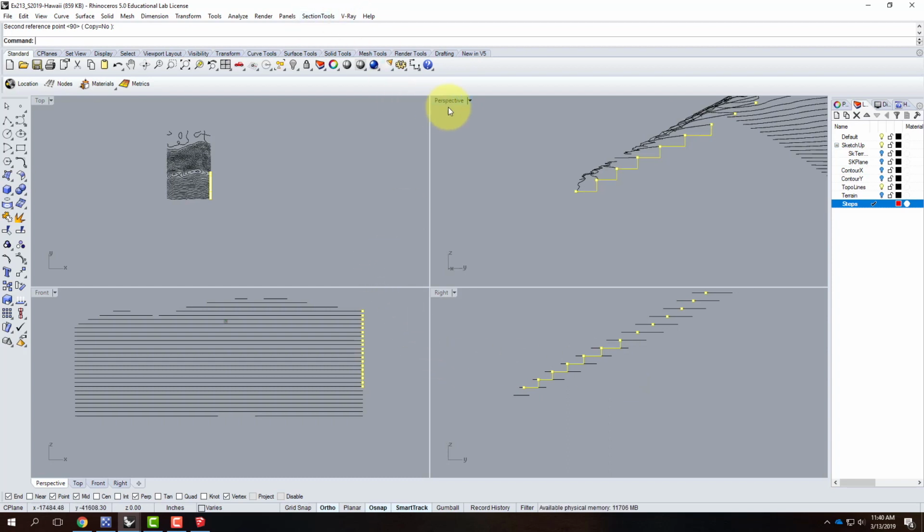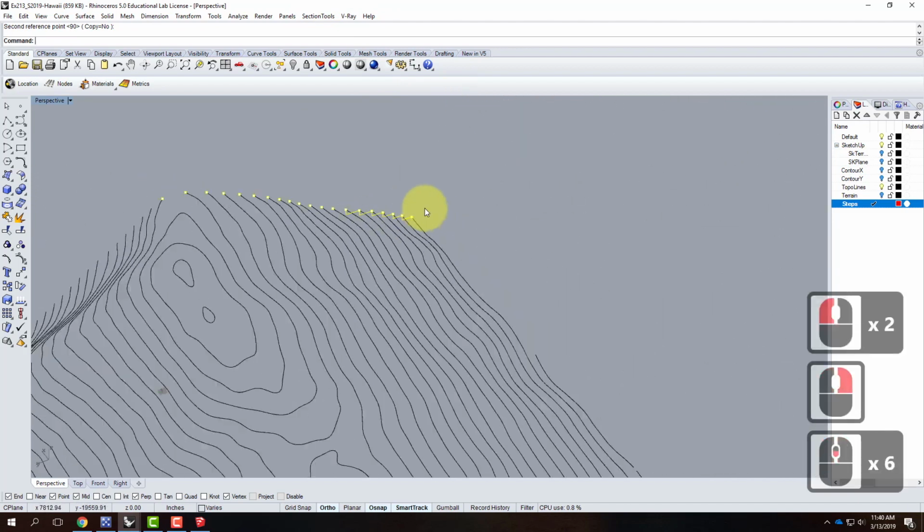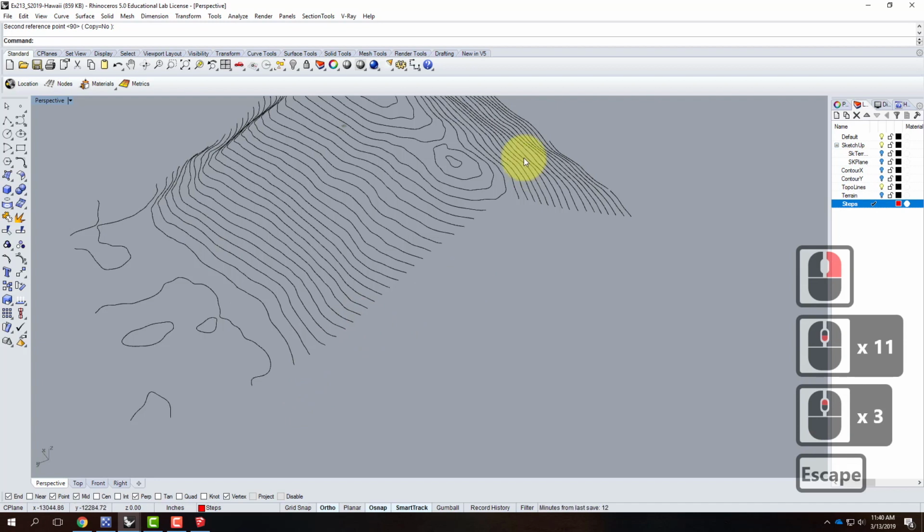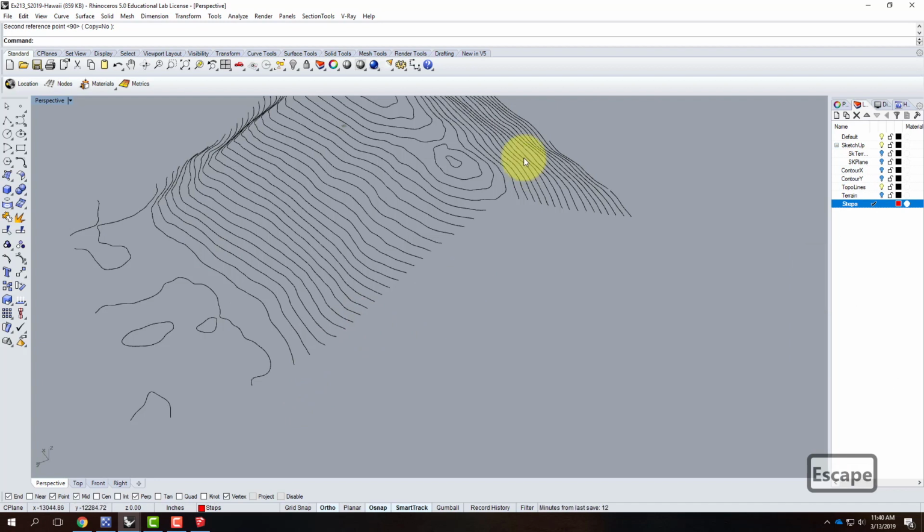The other method, and I'll switch over to the other side here to show you that method. The other method was, instead of creating the points and rotating them flat, switching the drawing plane from being flat to being along the side of our model. And so that drawing plane is called the C-plane in Rhino. It's called the UCS coordinates in AutoCAD if you're familiar with that. And so I want to switch that to be along this side.